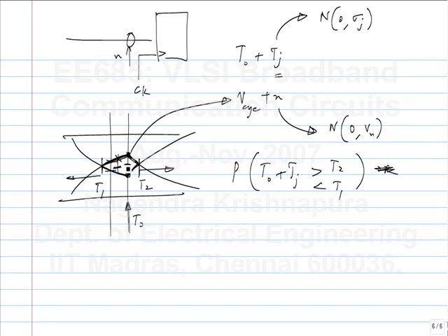Okay. It's hard to describe verbally, but hopefully you got the idea of what's going on. So if I am sampling here, I can move the sampling edge because of jitter, and if I have moved it to this point, then the signal amplitude is smaller, so it can go down more easily with the same amount of noise. So there is some distribution of two variables, both the jitter and the noise that is added to the eye. Okay, so that gives you the bit error.